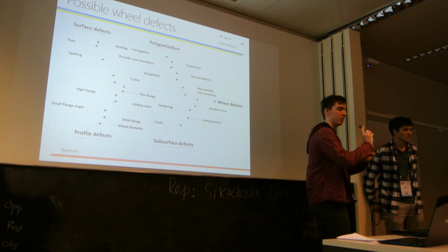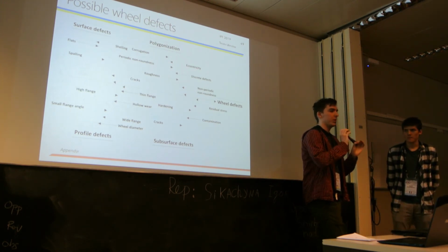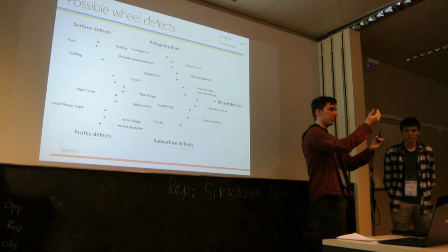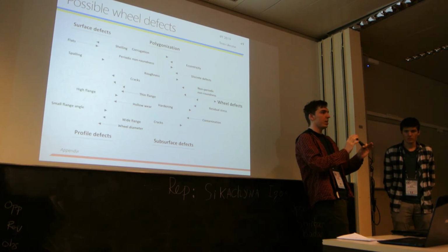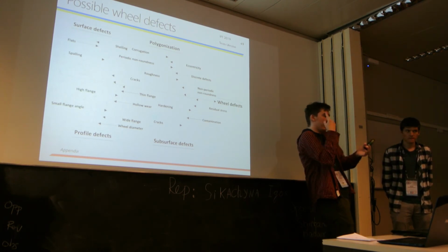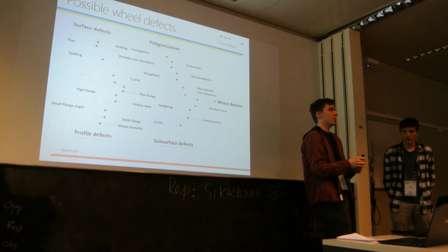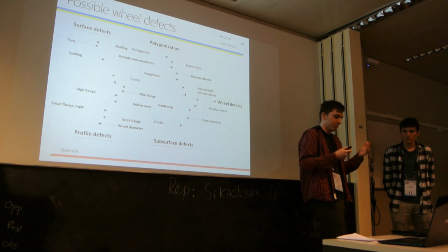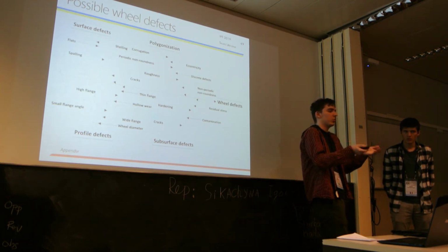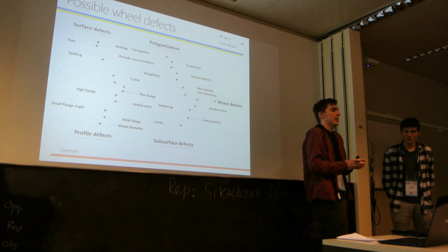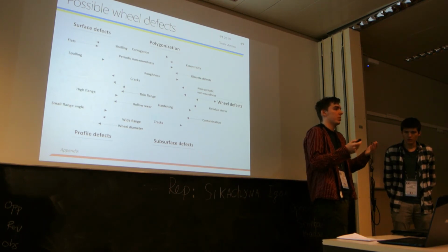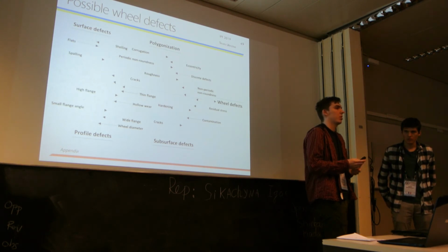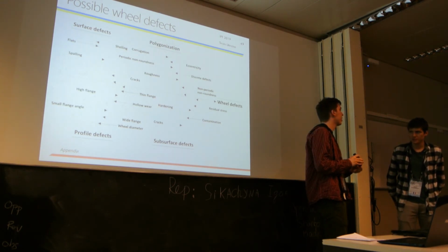So there is a hit on each side. We understand that one wheel may have multiple defects, which will produce, for example, two different signals for one wheel revolution. This case can be viewed as two different wheels with one defect, essentially. And this goes to the amplitude coefficient of the train. So even if a train has multiple defects on one wheel, we already account for that in considering its amplitude characteristics.